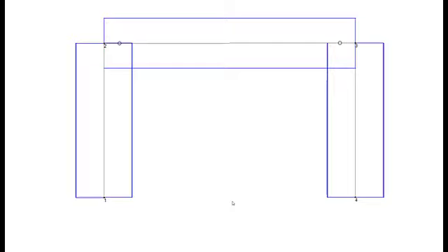However, the distortion of the results that we are facing is due to the fact that the end of the beam is assumed to be connected to the center of the column, and thus we would need to take care of this distortion. We will see in a moment how the master-slave concept can help us solve this problem.